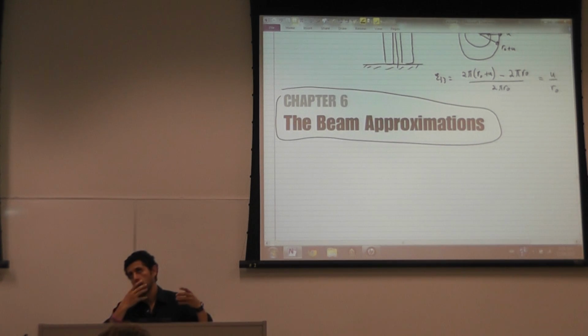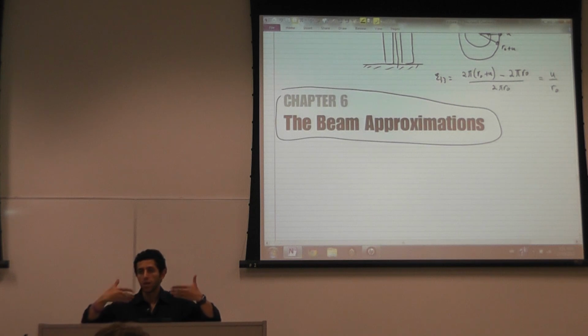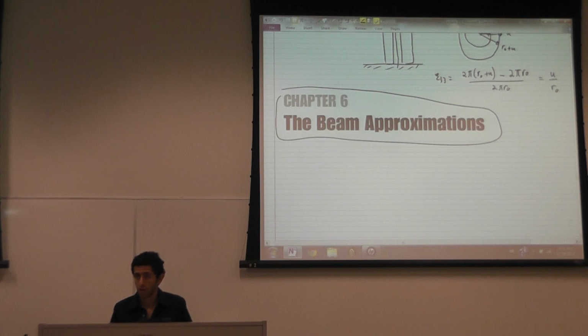When you take a thin beam to the lab and model it, usually you consider the beam as plane stress as long as you're not applying forces on the beam to the outside. Okay? As long as you're not worried about the webs of beams, a web of an I-beam, as long as you're not considering buckling or out of plane movement of that web, this is a plane stress condition.